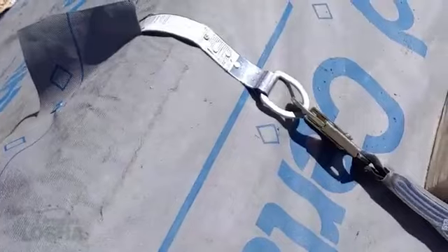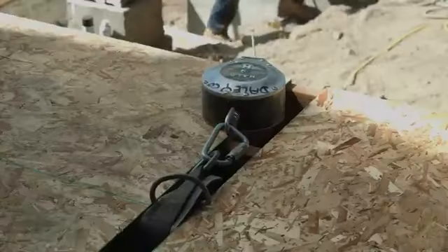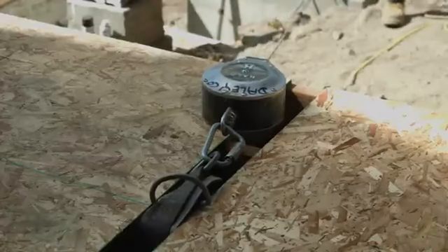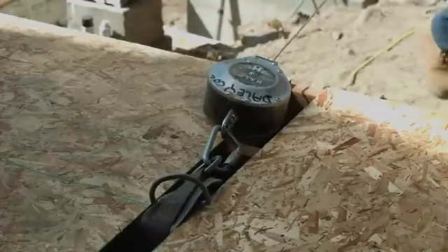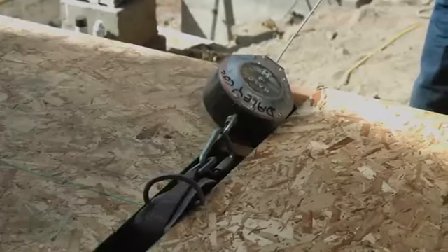Common anchorage points in residential construction. A lot of times we'll see people tying off to the peak, putting an anchor nailed to the sheeting on the peak of the roof. We've also seen straps nailed to the floor, typically used with the self-retracting lifeline styles. There are ones that span across several trusses for anchors.